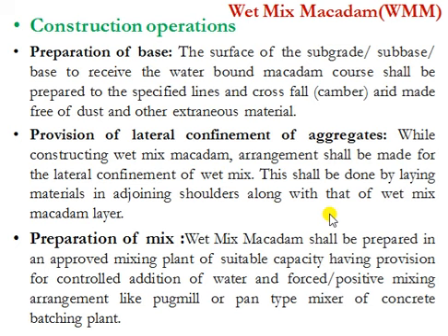And here the optimum moisture for mixing shall be determined in accordance with IS 2720 Part 8. So after replacing the aggregate fraction retained on 22.4 mm sieve with materials passing 22.4 mm and retained on 4.75 mm, while adding water, evaporation loss shall also be taken into account, and the mixed materials should be uniformly wet and no segregation shall be permitted.